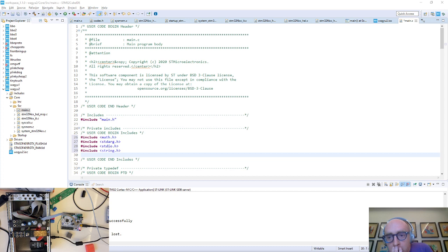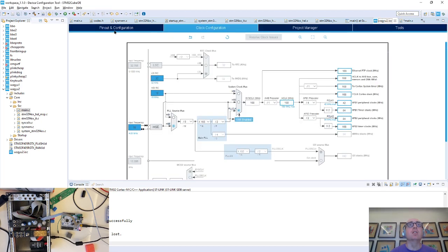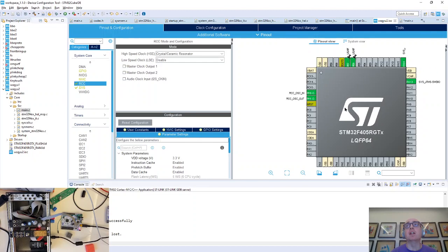This is not doing a great job of selling me on STM32 IDE. Yeah, as I said, it must be horrible for the team who are developing it because I think they're valiantly trying to do a good job. And I actually think it is the best way of bringing up a chip from nothing. I mean, what's cool is I can bring up any of their chips, of which there's a bewildering number. And rather than leafing through a data sheet for tables after tables after tables of what you can and can't do with each pin, I can actually point at it and say, right, I want these pins to do these things. And you get into a rhythm where it's actually incredibly helpful.